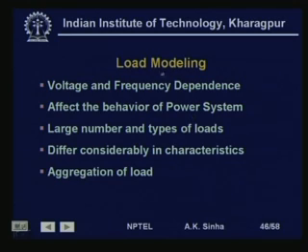Next, we will take up the load modeling. Loads have voltage and frequency dependence, and because of this change in voltage and frequency in the system, the value of these loads changes and therefore they affect the behavior of the system. We have a large number and different types of load which differ considerably in characteristics, and most of the time what we do is at any particular bus we aggregate these different types of load into a single load model.